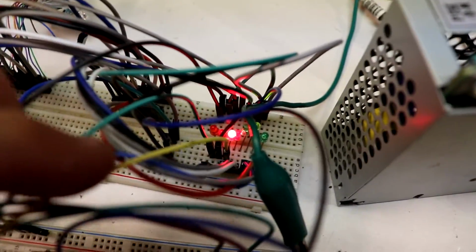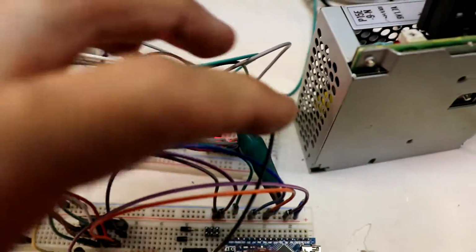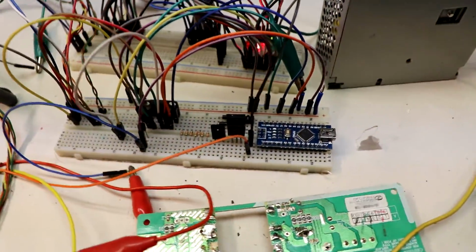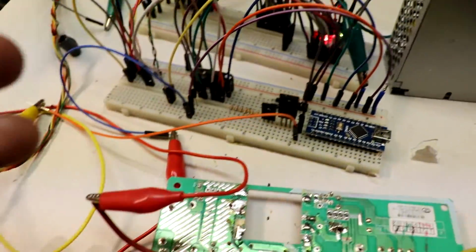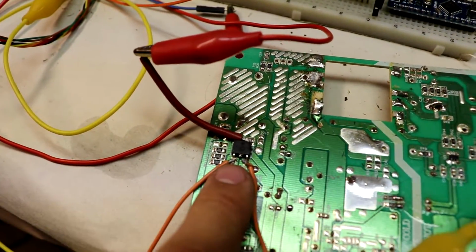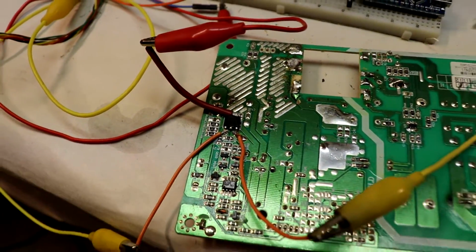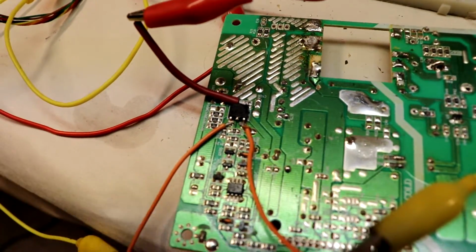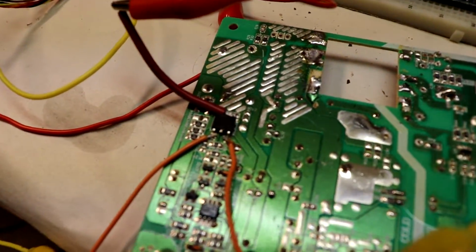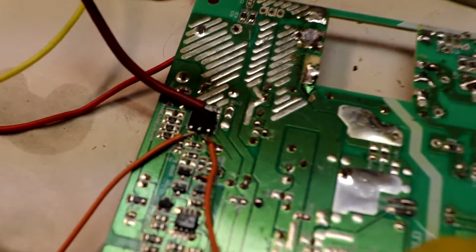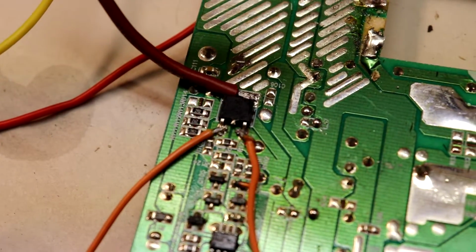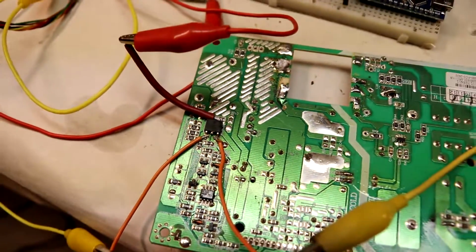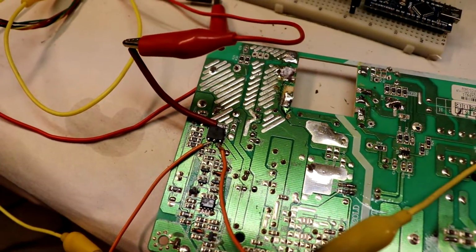But it's a different story for pin 3. Pin 3 is the enable pin, like I said, and pin 3 has to go through this N-channel MOSFET. So the board is irrelevant. I just kept the MOSFET on there because I was too lazy to take it off. But this N-channel MOSFET is designed to turn on at a fairly low voltage. I think it was maybe 4.5 or even lower.